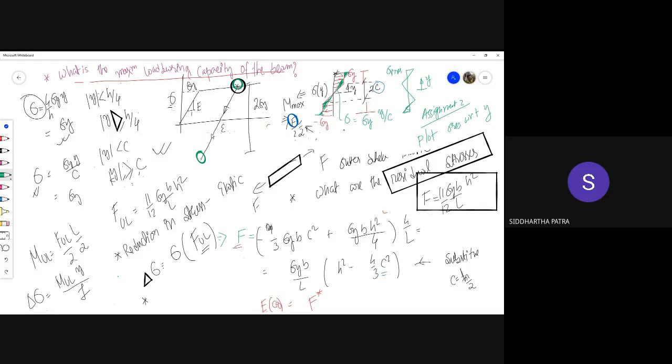And because the unloading process is totally elastic, I'm considering what sort of stress I would have got if I had applied the same force that causes an elastic core of certain size, and the material would have deformed elastically. So that stress I'm calculating, and that stress needs to be subtracted. The material is actually not going beyond sigma y.